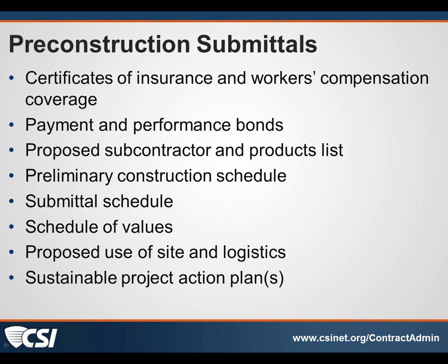If you've asked for it in your documents, and this information usually comes to you from the owner as to what they want for the limits of liability and insurance coverage. If it says they want a $5 million policy and that insurance certificate comes in and it's a $2 million policy, there's no need for you to forward that on to the owner. You need to return that back to the contractor, copy the owner, tell him you're not complying with the documents.